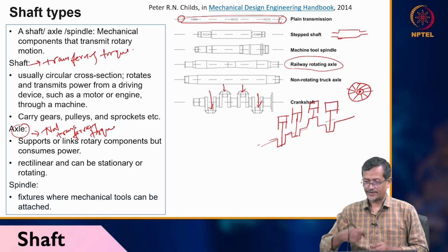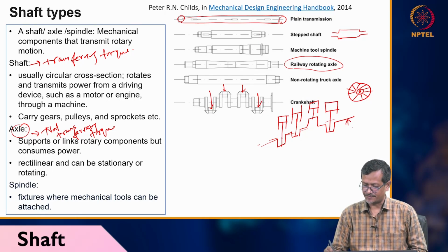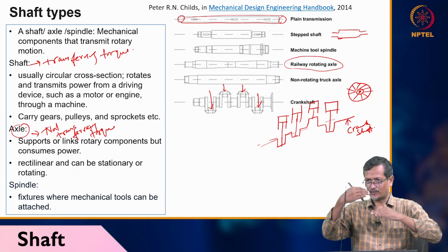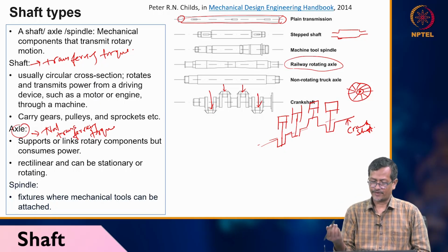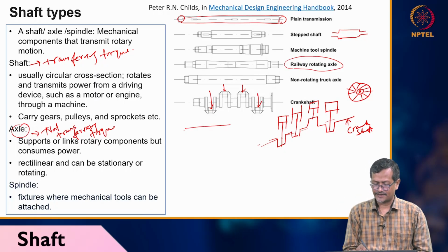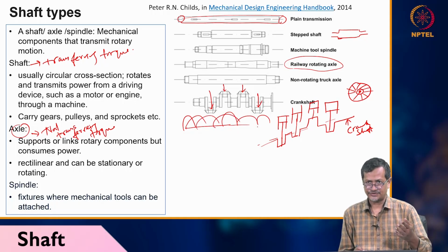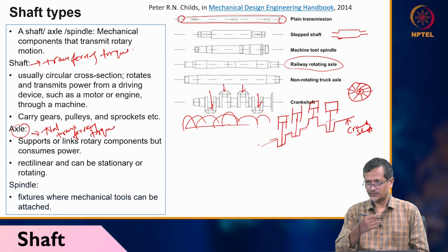Okay, so if you rotate this crankshaft, the pistons will be moving one by one. If you have only a single cylinder, in that case you are getting pressure pulses like this, or forces. But if you have multiple cylinders, your forces will be more smoothed. That's why very big engines have multiple cylinders. Many types, V engines, inline engines, so many types of IC engines will be there. So that will be smoothing your power.